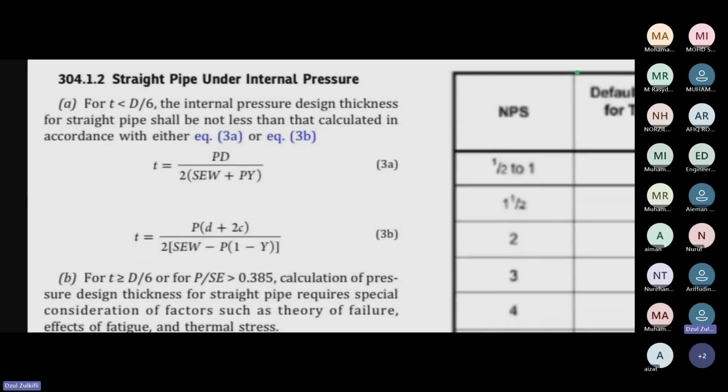So stiffener is covered in the sense that, let me think. Whether you need a stiffener or not is covered by normal ASME calculations. Okay, so the normal ASME external pressure calculation will tell you whether you need a stiffener or not and where you need to put that stiffener. As to how big the stiffener ring has to be, that is also covered by the ASME code, I think.